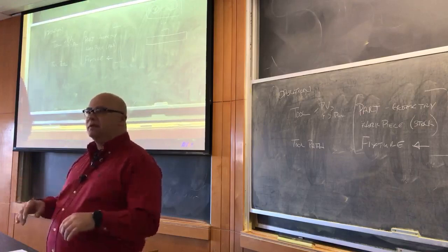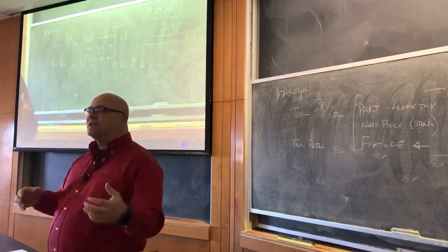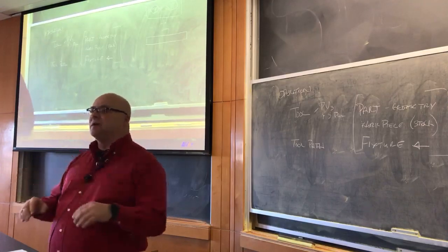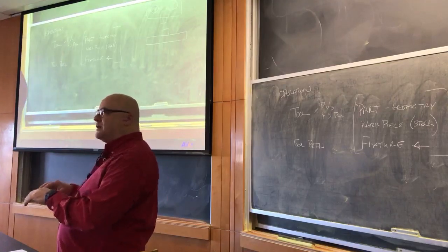Which is one of the reasons why we don't let you guys write G-code manually. It's one of the reasons that when you need to fix your program, even if it's a simple fix and you can just go edit the G-code, we tell you to pivot your feet, go back to the CAM software and fix it in the CAM software.